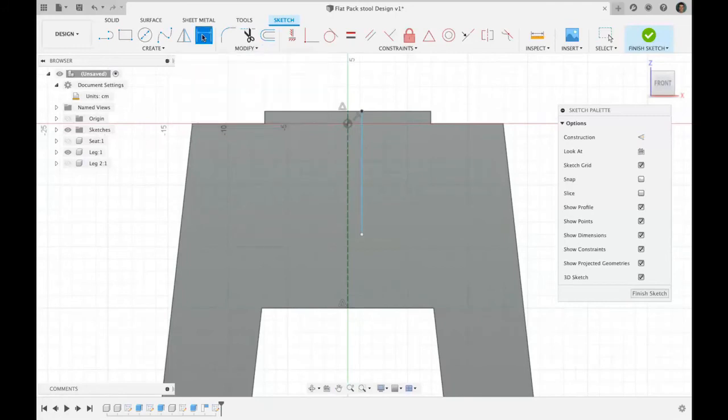So I'm going to select my dimension tool. And if you recall, I said the height of this was our stool height divided by 3, from just underneath the stool point to here. So we need to do that plus the thickness that we go into the stool. I'm going to click to select this line, and I'm going to make a double bracket and say stool height, which is what we said, divided by 3 as the first part.